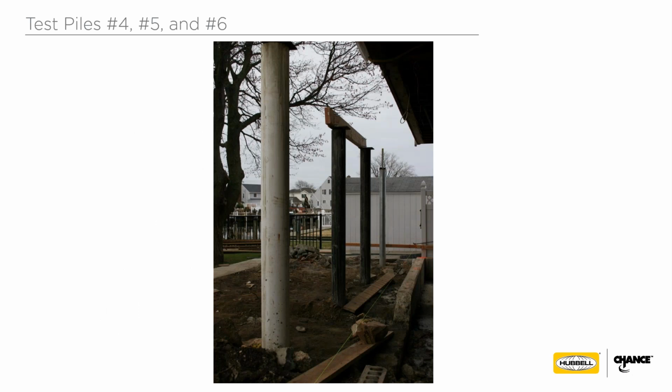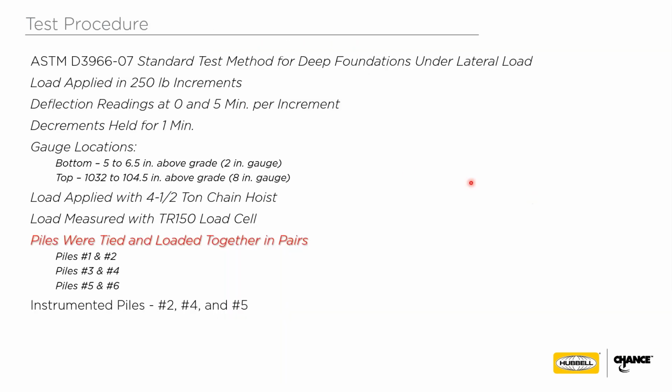Here's some of the piles. This is the pile, the grouted shaft. We took the PVC casing off for the test. And you can see some of the ways that we were attaching the piles to, again, test them together in pairs. So we just followed standard ASTM methods for deep foundations under lateral loads. Kind of go through these details.